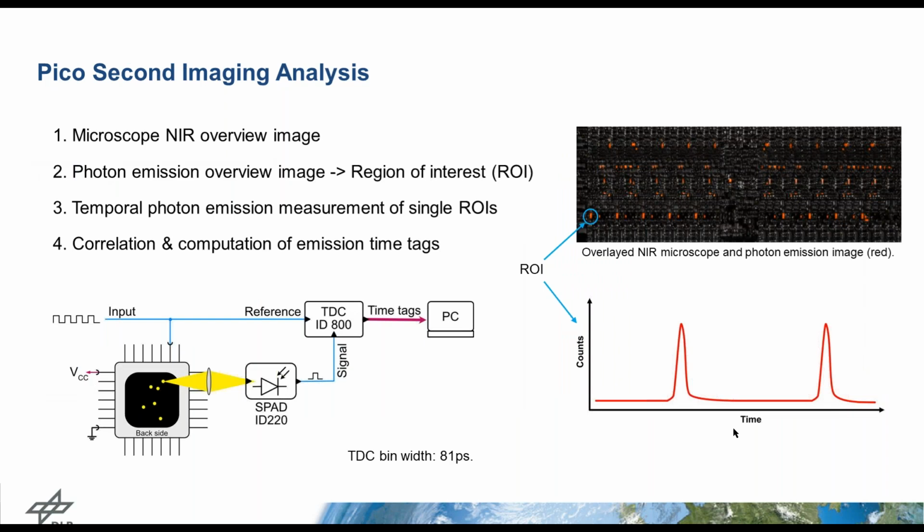This is a really nice technique. What you want to do here is you are not interested only in the information of when a transistor emits a photon, but also how this time event changes. Is there a delay when we change something, let's say in the logic before? Let's say another transistor is involved, and so we have an additional delay in the propagation. So the question is, what is the limit for resolving such a difference in the signal propagation?